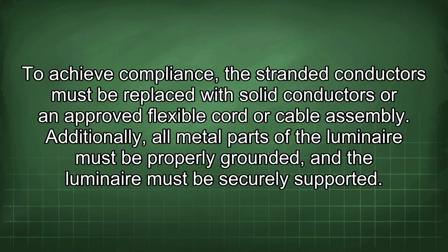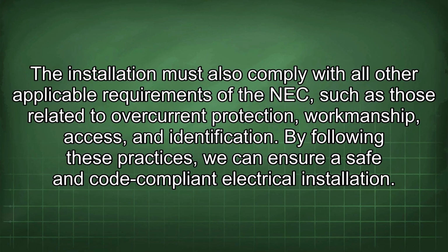Additionally, all metal parts of the luminaire must be properly grounded, and the luminaire must be securely supported. The installation must also comply with all other applicable requirements of the NEC, such as those related to overcurrent protection, workmanship, access, and identification. By following these practices, we can ensure a safe and code-compliant electrical installation.